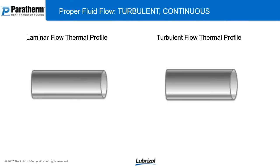So let's take a closer look at this from a graphic standpoint. Proper fluid flow. We're going to talk about turbulent and continuous flow here. You want to make sure that you have those two areas, turbulent flow and continuous flow. So the two different areas we're going to look at, you have your turbulent flow thermal profile, and then the opposite of that, a Reynolds number below 10,000 is either going to be transitional or laminar flow. And the good way to think about laminar flow is the fluid itself is kind of moving as a plug through the pipe, okay? So you don't have good movement of fluid.